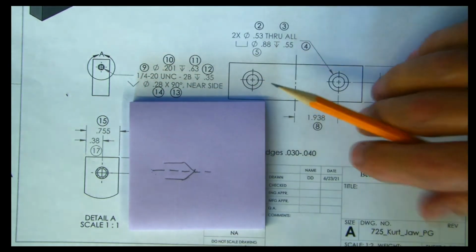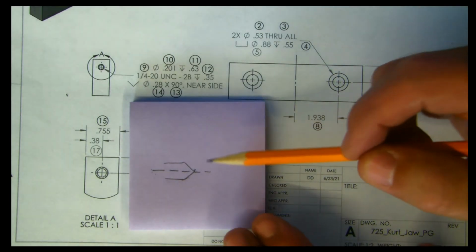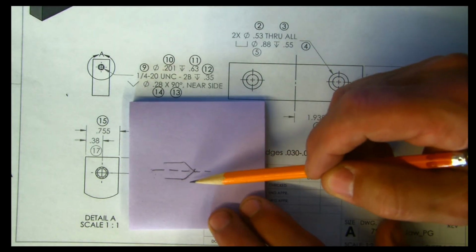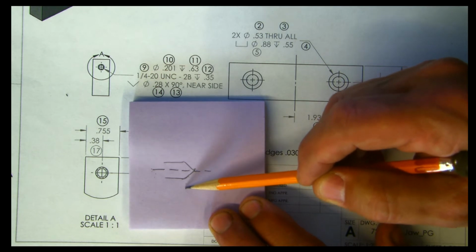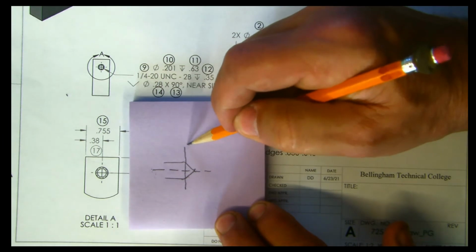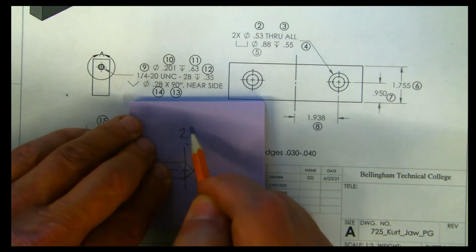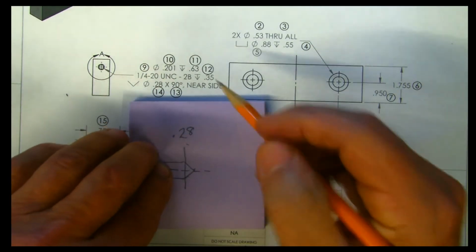because this drill, since it is rotating, is going to machine just like we do on the lathe, where anything we do to one half of the part is repeated on the other. Okay? So what I want to do here is draw a line at a simulated 0.28 inches.